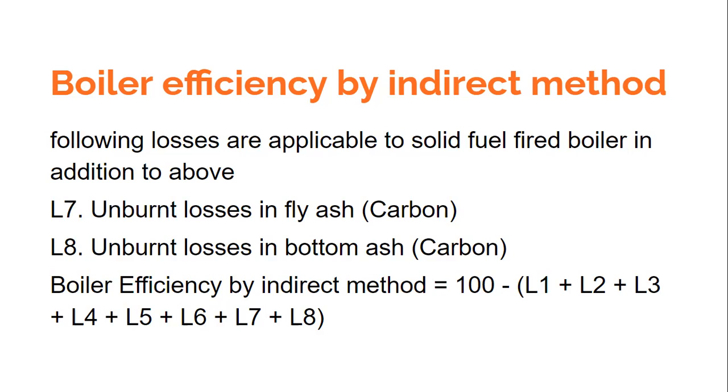If you look at this boiler efficiency calculation method, you would easily understand that we have calculated boiler efficiency by doing an energy balance. We have found out where the losses are happening, and then we can figure out where one should intervene. If you want to improve the boiler efficiency, and we know, for example, that there are major losses via the flue gases, then we can make corrections. What corrections we should make, we'll be discussing. But we can make those corrections, and then that particular loss would be reduced, and your boiler efficiency would be improved.